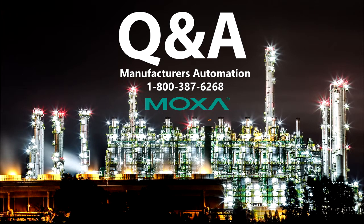The associated apparatuses for that matter will obviously depend on the regulations that are required for an offshore operation. You'll probably have to have NAB or DNV certifications that have to be marine grade. The entire unit will have to be IP66 minimally, Class 1 Div 2, and everything attached to it will have to fall under that categorization as well. So wires, busing, or however it's attached to the operation, need to be insulated properly.